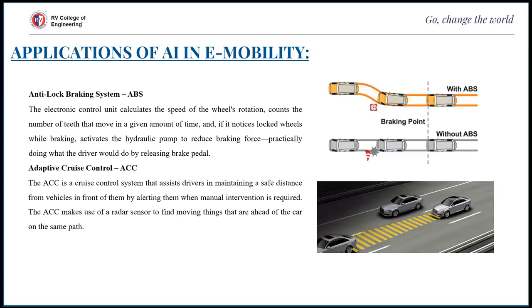But if the driver is startled by the pedal's vibration and releases the brakes before the application of brakes, then it leads to accidents. Because of this, some automobiles also use braking systems where they have an emergency braking aid. That is, the front axle is first lowered and then part of the load is transferred during the brake, which increases the vertical force of the wheels significantly. When using ABS, the steering wheel also vibrates, so it is best to hold it firmly with two hands.